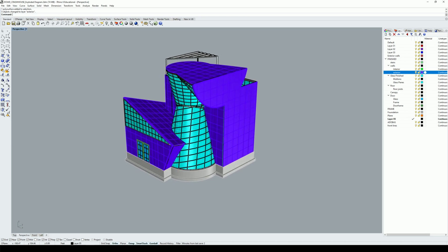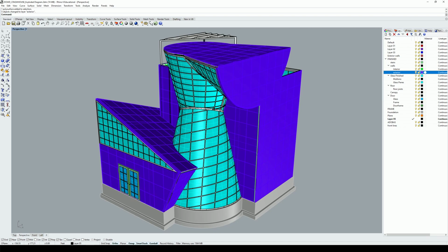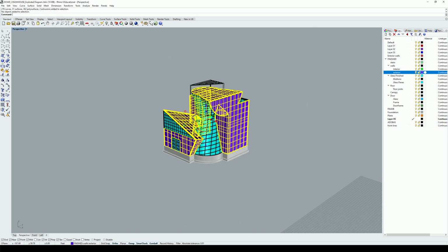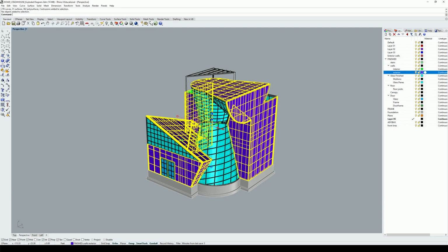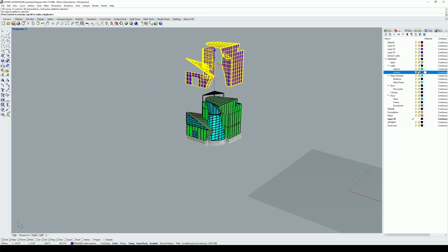we're going to select some of the layers you just created. For example, I'll start with this exterior layer since that's what we were just talking about. I'm going to right click on it and say select objects. As you can see, all those objects are selected. Now I have the gumball tool turned on, and that's on the bottom of your screen. This allows me to just click on the top arrow here and drag it up.